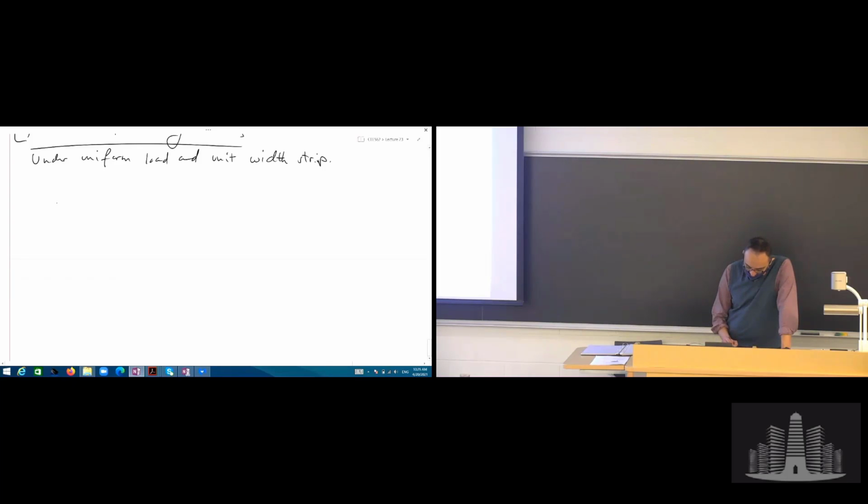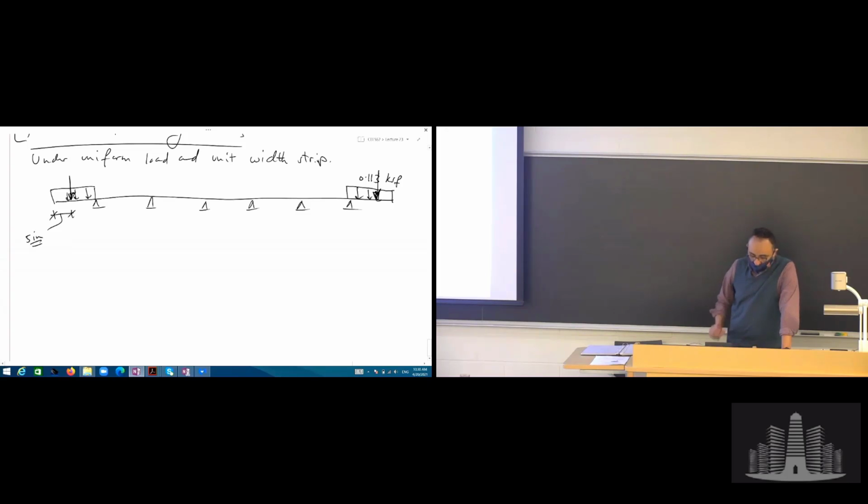So for example, when you look at how the dead load is placed on the bridge, we have the overhang, and we have 6 girders, 1, 2, 3, 4, 5, and 6. The overhang has a little bit higher uniform load because of its higher thickness of 9 inches, and that is 0.113 ksf. There are also point loads here and there, which is the barrier, placed at the CG of the barrier, which was given to us, if you recall, at 5 inches from the edge. So that's where the centroid, the line of action of the weight of the barrier is. And this is going to be 0.32 kips per foot.